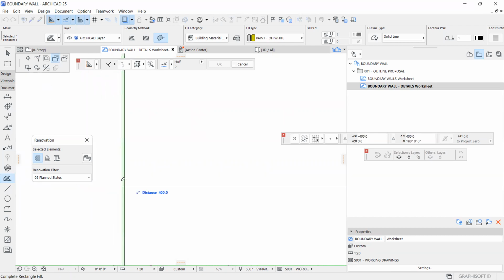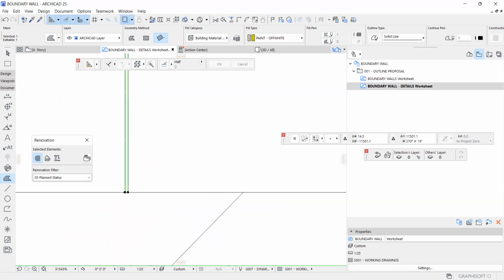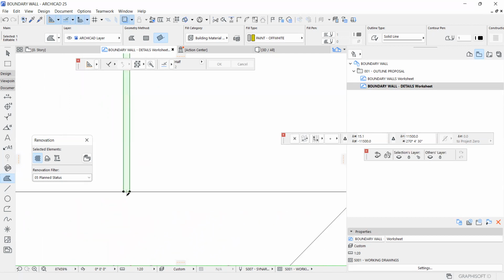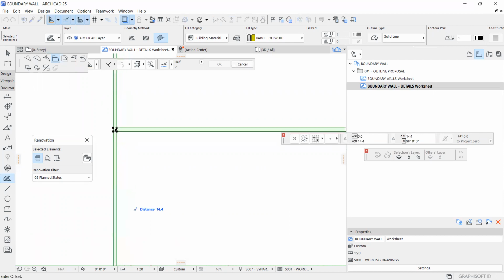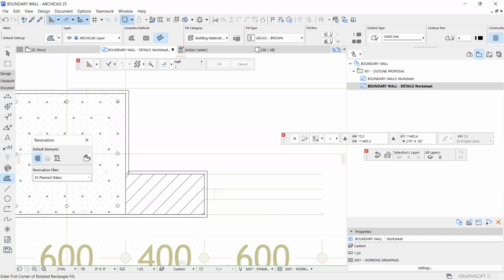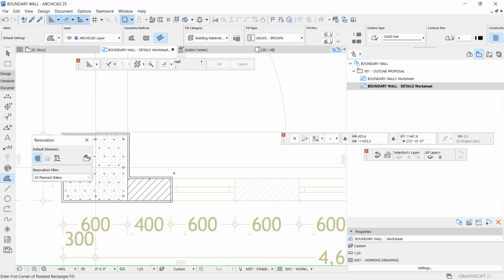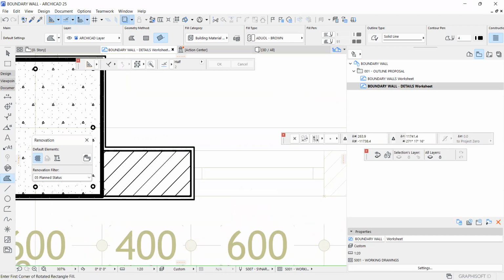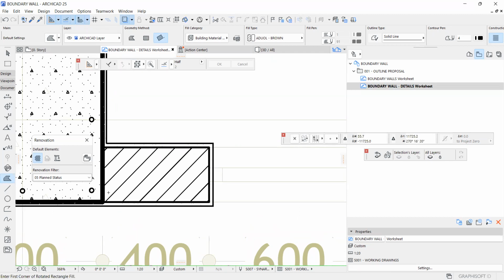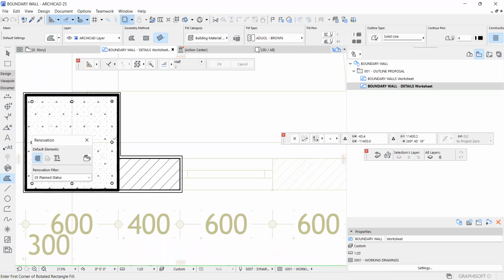Once again, at that point, our paint is clashing with masonry. So where paint clashes with masonry, masonry is given priority. We'll discuss prioritization later, but at least that gives you an idea of what we have. Okay, let's activate the true weight and see. So ideally, that's what we should be seeing in terms of your detail.